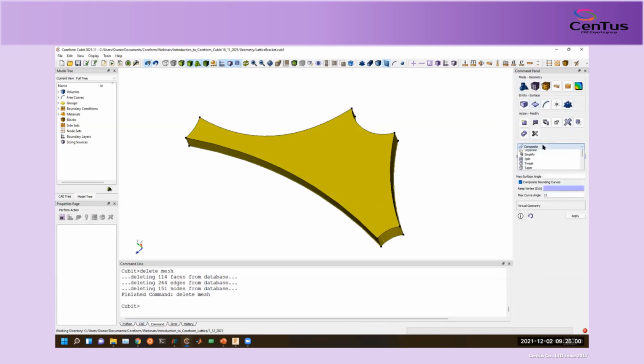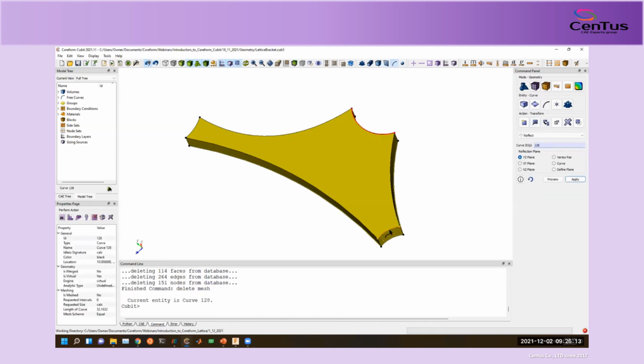So in preparing the CAD model, I'm going to split curves. I'm going to get a dividing curve that divides maybe these faces in halves. So I can take a curve, modify, partition, and cut it in half.